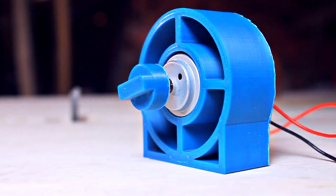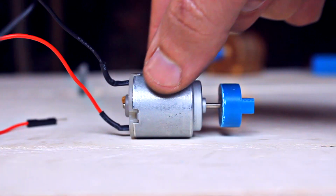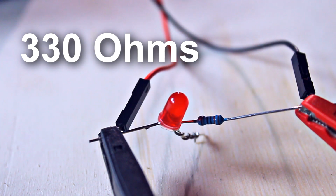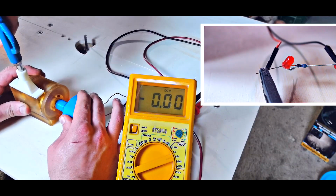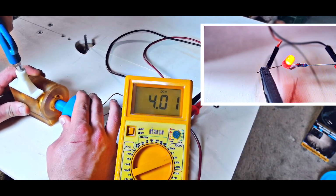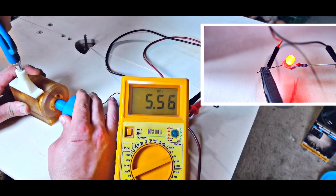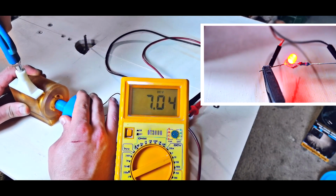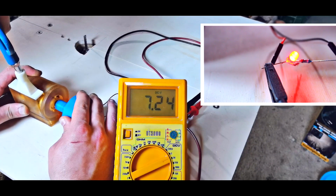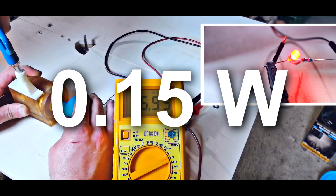Next, I printed a motor support and an axis union which I used to fit a high-speed DC motor on the turbine. I used this and a load of 330 ohms to measure the power output of the turbine. The turbine produced about 7 volts with the load, which gives us a power output of about 0.15 watts. As you can imagine, this power output can't do much. But that's not my goal anyway.